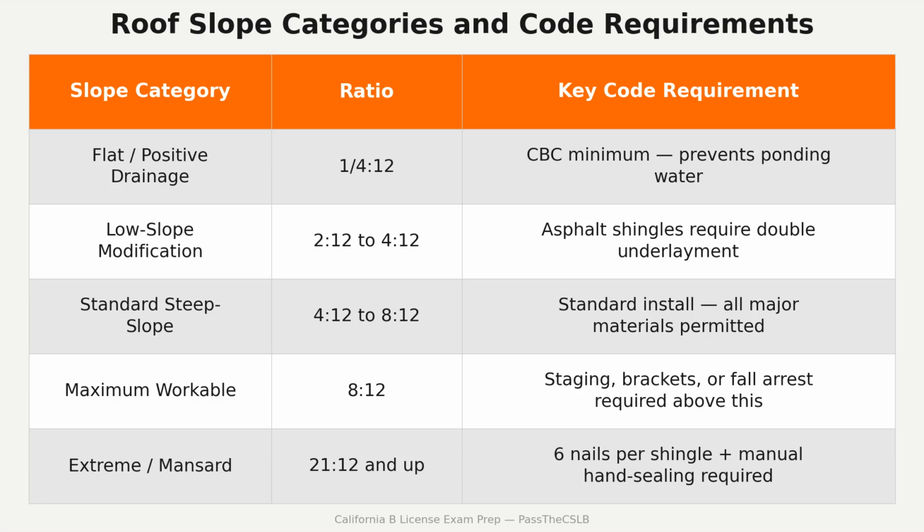Flat surfaces with no aerodynamic profile. In a high wind event, they catch lateral pressure like a sail. That vulnerability is the reason the hip roof was developed. A hip roof eliminates gable ends entirely. All four sides slope downward to their perimeter walls. No flat vertical faces. That continuous sloping profile deflects wind load rather than catching it. Hip roofs are the standard in coastal and storm-prone zones for exactly that reason. The trade-offs are real. More complex framing, higher cost, less usable attic volume. Official preparation resources identify those trade-offs as key content.